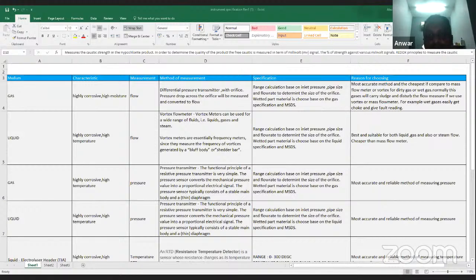The downstream control system will shut the valve, and it will not allow you to do the discharge until you get the pH back into control. So this is where the control system design has the responsibility to ensure that you only discharge according to the legal requirement.